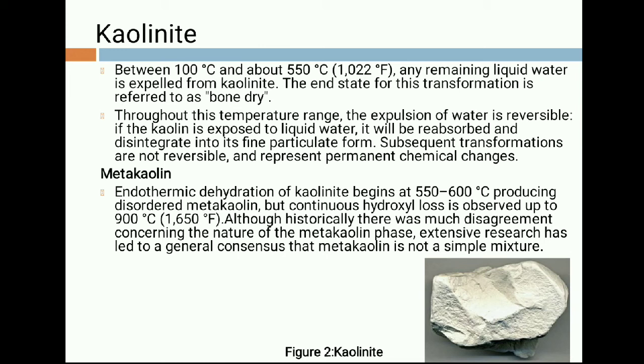Now let us see what is metakaolin. Metakaolin is basically a clay mineral which is used extensively in soil engineering based projects. The endothermic dehydration of kaolinite begins at 550 to 600 degrees Celsius, producing disordered metakaolin, but continuous hydroxyl loss is observed up to 900 degrees Celsius.